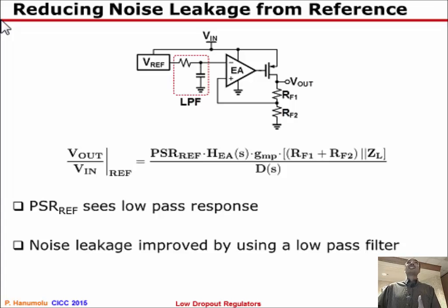So the current efficiency can still be maintained, but it boils down to designing the error amplifier with very small bias currents. Operating them in sub-threshold is what I have seen, and bias currents can easily be in the tens of nanoamps. I see, so just a narrow band, low power error amplifier. Correct. Now you can appreciate why the other question can be hard.